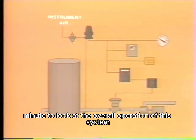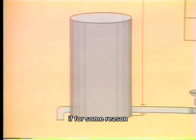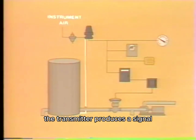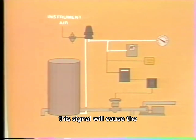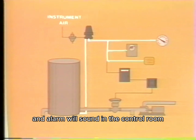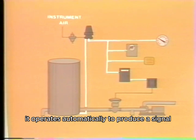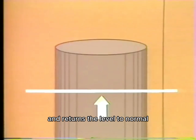Let's take a minute to look at the overall operation of this system in an automatic control situation. If for some reason the level in the tank begins to drop below the desired level, the transmitter produces a signal indicating a decrease in level. This signal will cause the indicator and recorder to reflect the change in level, and if level drops below a required limit, an alarm will sound in the control room. As the controller receives the signal from the transmitter, it operates automatically to produce a signal that opens the control valve. This increases the flow of liquid to the tank and returns the level to normal.